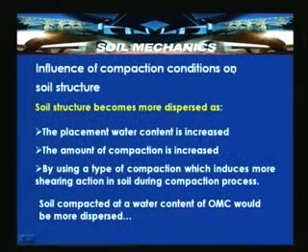So, influence of compaction conditions on soil structure, we can summarize. The soil structure becomes more dispersed as the placement water content is increased. So, on an average, if the placement water content is increased, the soil structure tends to change to dispersed. The amount of compaction is increased.